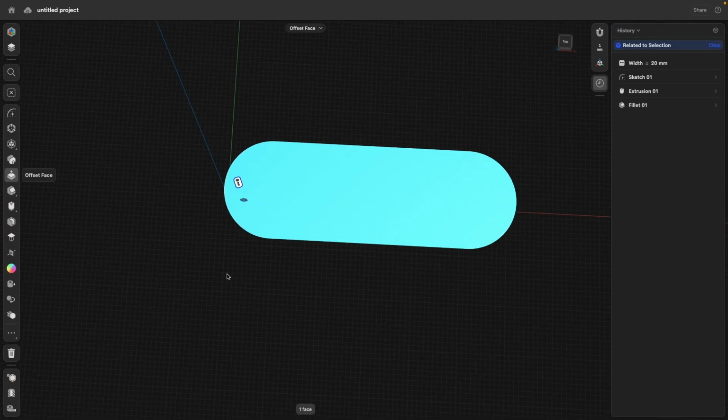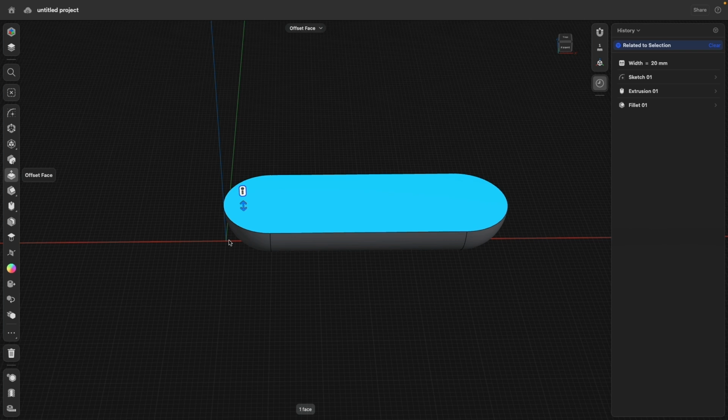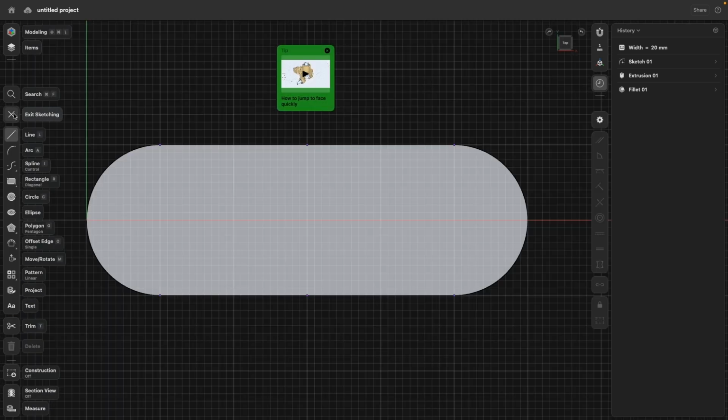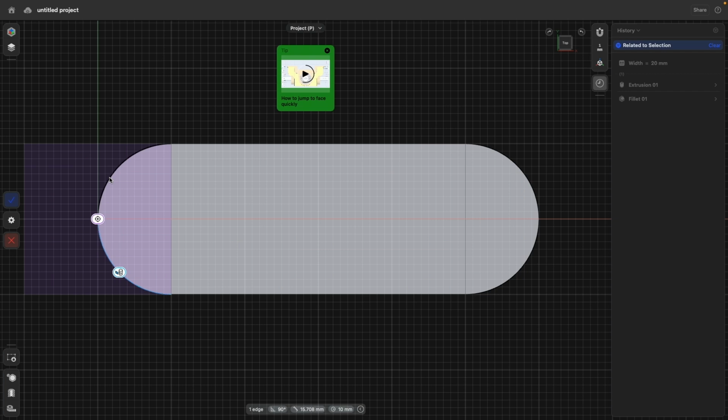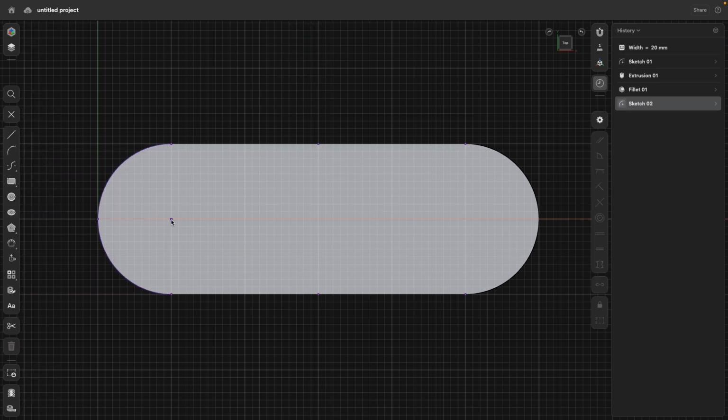On this top face, I would like to have a button. A button should have a center and an outer ring. Each one should be exactly the same proportion, so 50%. And I want everything to have an offset of 4 millimeters. So with this face selected, I can go to Sketch. Then I will project in 1 or 2 of these rounded edges because they're based on a G1 fillet.